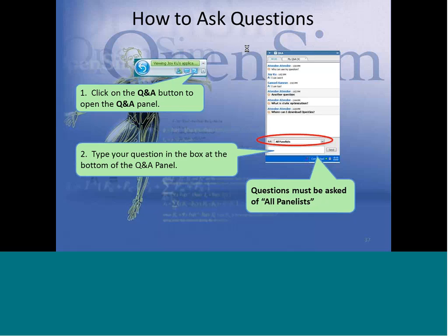I also reduced the shape factor for the active force length relationship, so that there was no active forces or hardly any active forces. You might also have to adjust the K passive shape factor, so that your muscle forces don't go beyond a maximum of about 1,500 newtons to 2,000 newtons.